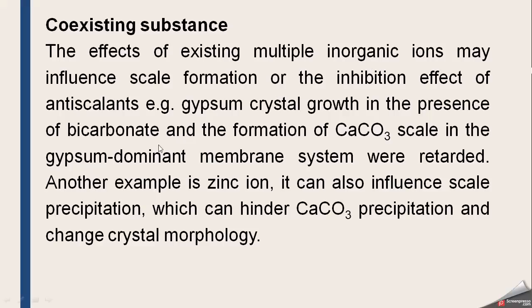For example, gypsum crystal growth, gypsum which is present in the water, in the presence of bicarbonate, and the formation of calcium carbonate scale in a gypsum-dominant membrane system were retarded. That is, if we have more gypsum, then the crystal formation of calcium carbonate is retarded. So less scaling will be formed due to calcium carbonate.